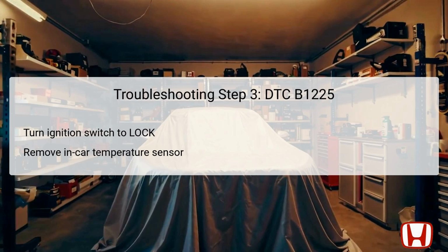This step is crucial as it ensures all electrical systems are deactivated during the diagnostic process, thereby minimizing the risk of electrical shock or component damage. Once the ignition is in the lock position, the technician should carefully remove the in-car temperature sensor for further testing. This process should be handled with caution to prevent damage to the sensor or surrounding components.